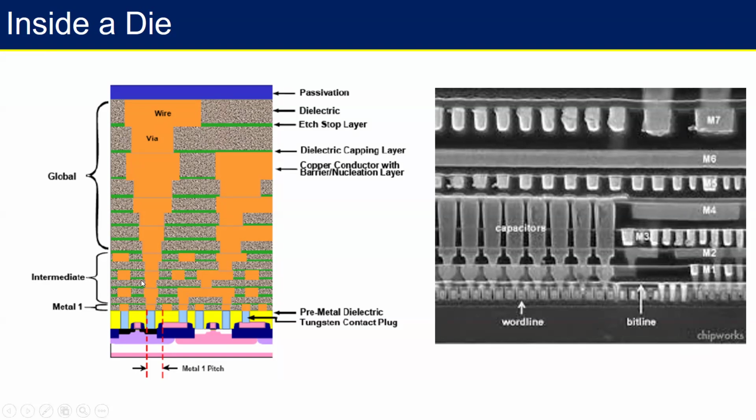And there the materials we see are largely, as you can guess, the orange portion is the workhorse of the semiconductor industry for the last 20 years. This is your copper. Before that, it was aluminum. But now it is copper, and these two lines don't need to talk to each other because this is a separate transistor, this is a separate transistor. So in between you put something which looks like concrete, but it is not, it is a dielectric. That means now you have a metal separation using dielectric, because it's a non-conductive medium in between.